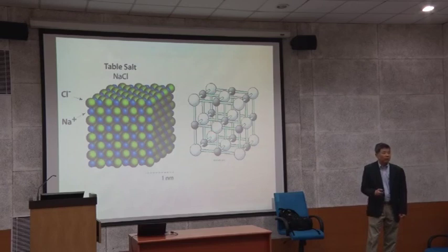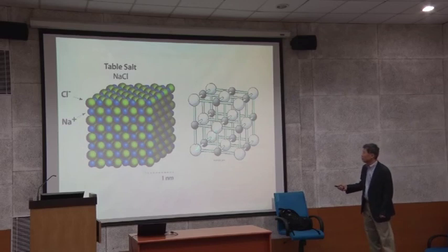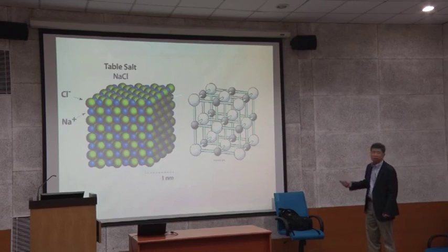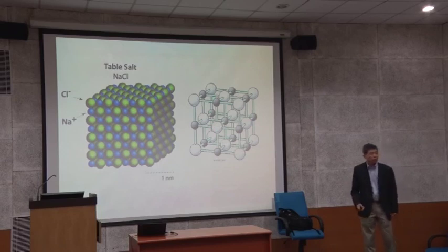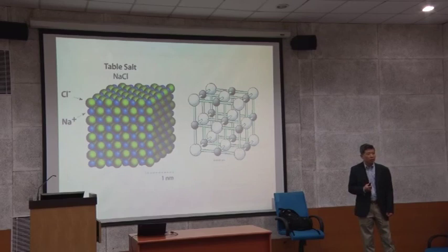But X-ray diffraction is not only getting the information of these lattices, which means your lattice parameters of the principal axes, and the angles between these principal axes, alpha, beta, and gamma. But you can also get information on atomic positions and what kind of atoms are located there, because of your structure factor. The structure factor depends on your atomic position and type of atom, which contribute to different intensity of the peaks.